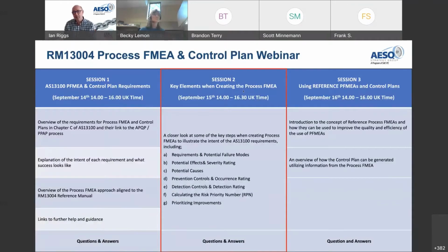Okay, so on yesterday's webinar, we covered the requirements that are in 13100 related to FMEA and control plans and how it links into APQP and PPAP. We also gave a high-level overview of what we expect to see in a process FMEA.